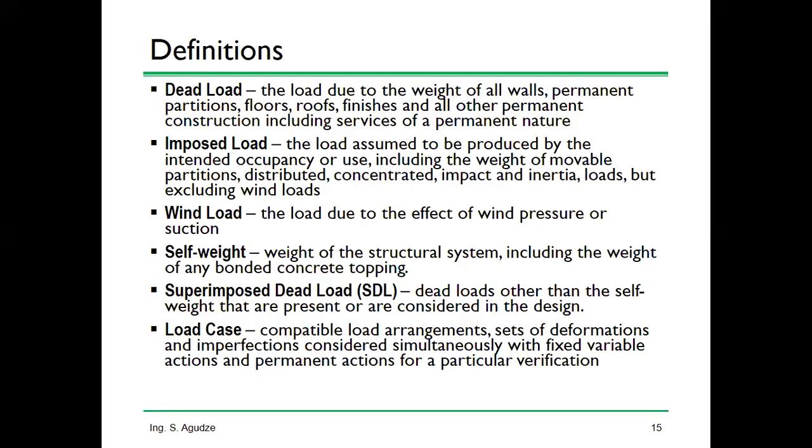We know about dead load. That's the permanent weight of all permanent elements. Okay, that's dead load. You have done it, so I don't want to speak too much. Imposed load has to do with the use and occupancy of the structure. If it is a store, the imposed load is different from a classroom, is different from an office, and that is what you find in the BS 6399. We also have wind load due to wind effect, right?